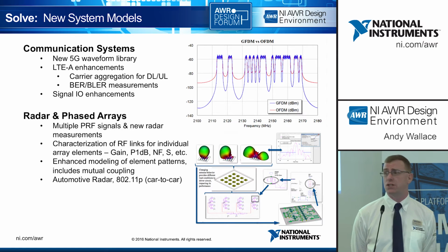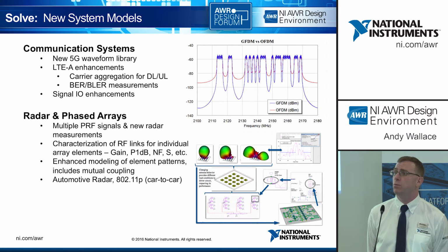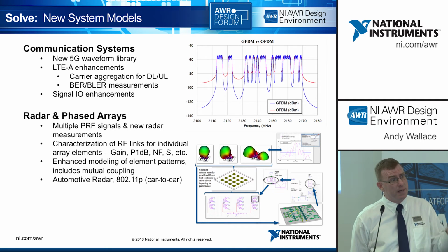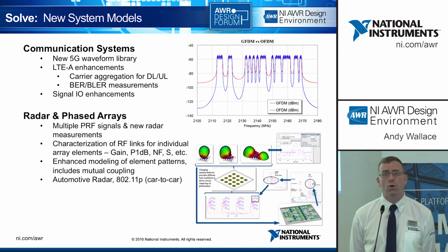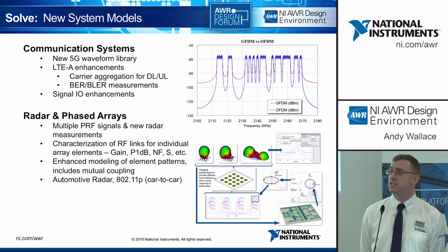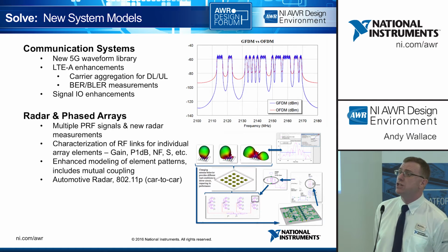We have a lot of the modulation libraries that are used in the simulation world, but now at its extracted level. So if you have amplifiers, for example, in Microwave Office, they come up as a behavioral model into the sample time domain world. You can have printed filters or surface mount component filters in the sample time domain engine, running sample time domain engines on the frequency domain results. That's all extracted automatically for you.